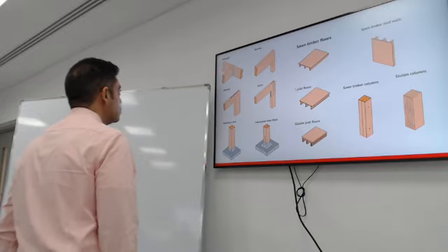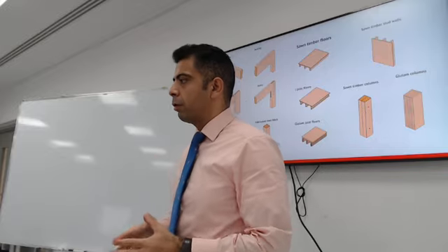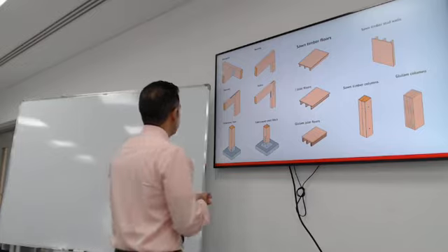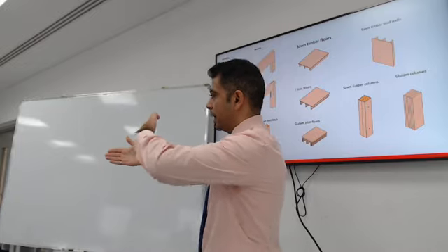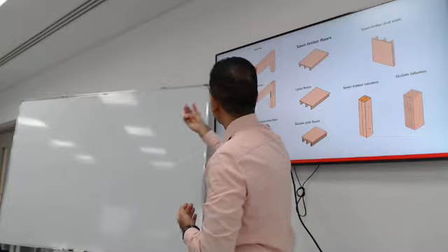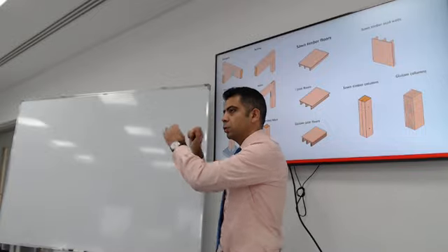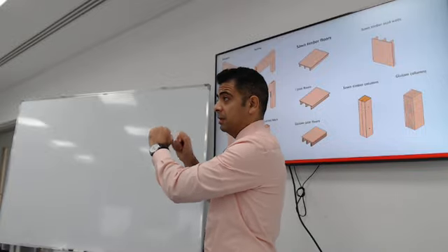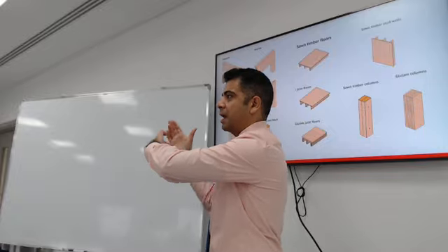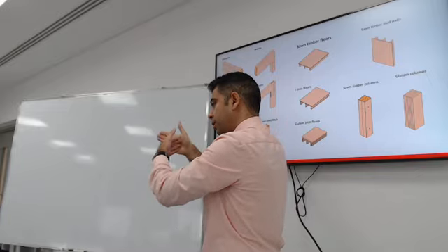I want to show you some structural elements that you can form with wood. You can have a beam supporting a joist or a beam supporting another beam using what's called a hanger. Do you see that steel part with the black holes? The holes are where you can drive nails, and it creates a nice place where the joist can sit, and it will be hung off the perpendicular beam. That's why it's called a hanger.